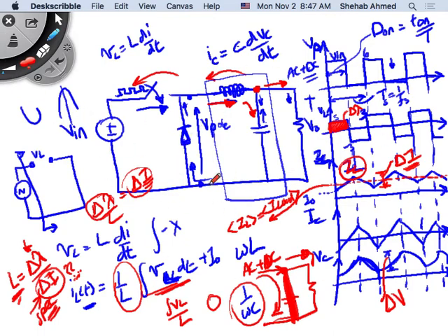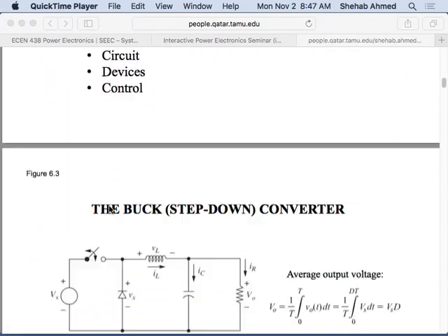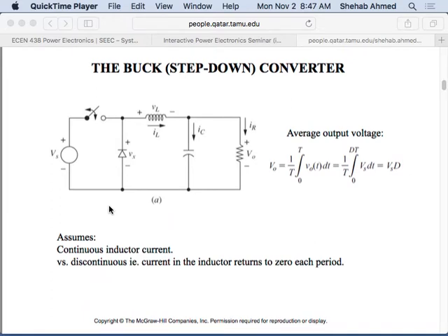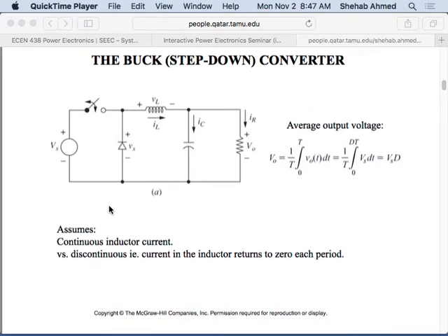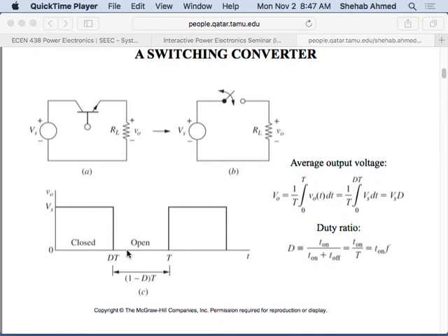So is everybody okay now with the buck converter? This is a step down, or buck, converter. If we look at what they're saying in the textbook, let's go through how they explain it. They talk about the output voltage waveform, and again, nothing changes, because the Vx waveform looks like this pulsed waveform, correct?